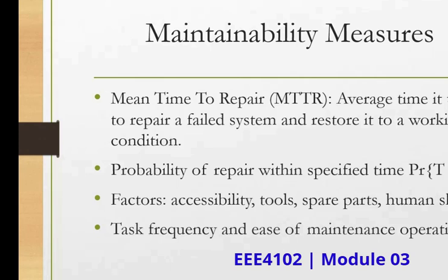Then we also look at the tools. Tools and spare parts are very necessary, tools readily available. You make sure that the tools and the spare parts that you need are available in case the components fail, so that you don't wait for the equipment to stop running and then find you don't have spare parts. That's when you start thinking of buying or ordering spare parts, and that is not good for an engineer to do.